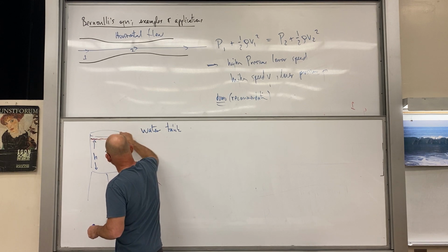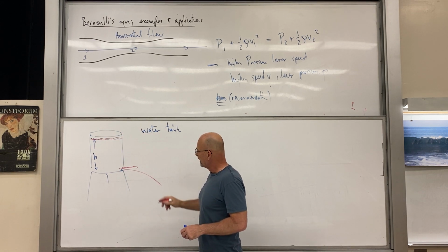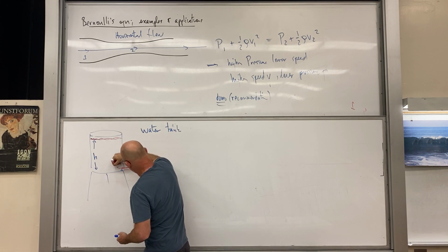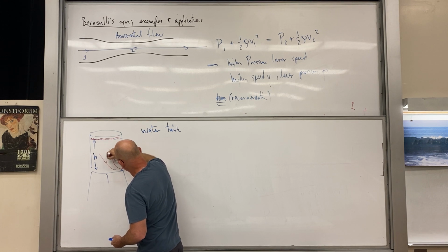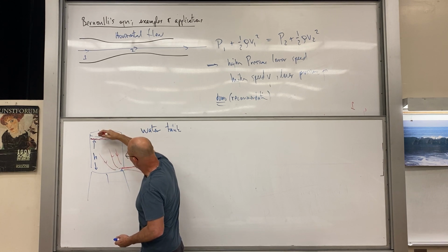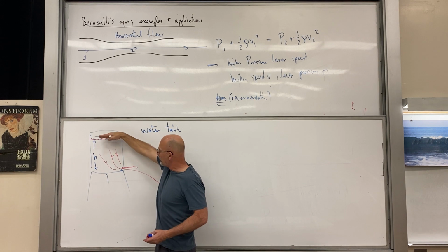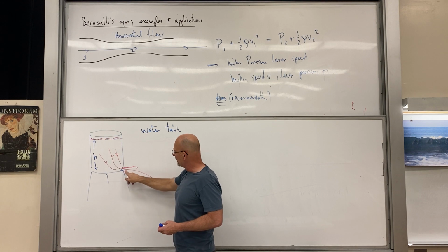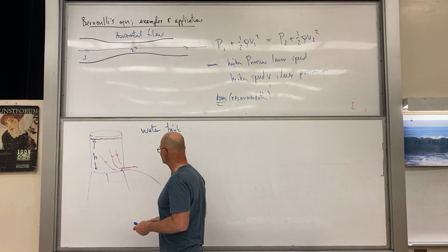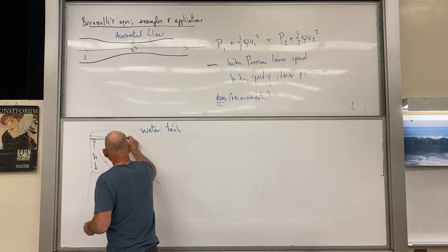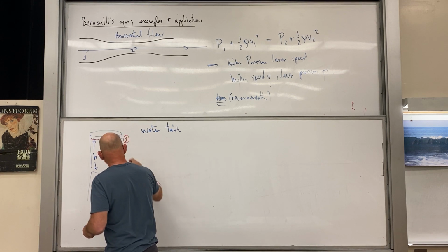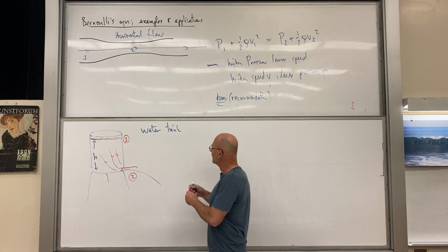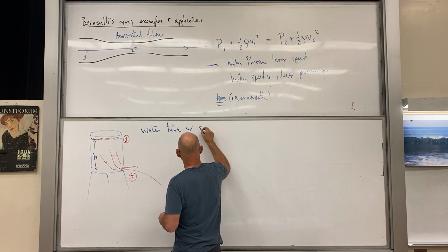And we have water at the surface. And we can imagine this water coming here via a smooth flow. What's happening is water's shooting out and the water level is dropping, but it's dropping very slowly because of the small hole in the large tank. Okay. So we'll just label these points here: surface 1, and where the water is emerging 2. So with a small hole.